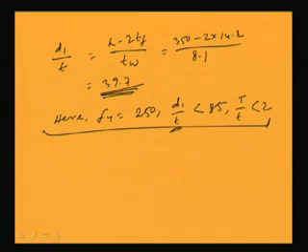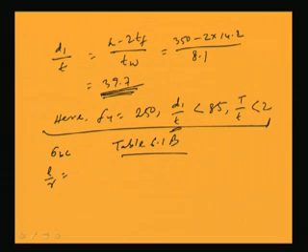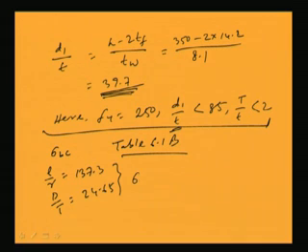So corresponding to this we can use table 6.1b and find out the value of sigma BC. For L by R equal to 137.3 and D by T equal to 24.65, which we have calculated, I can find out the value of sigma BC.